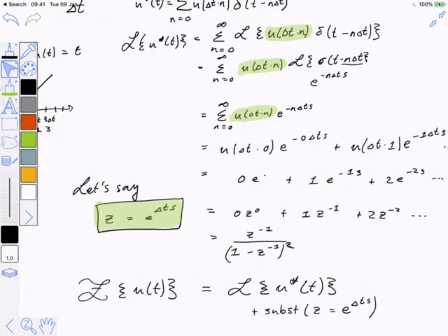Now, if you didn't go through this derivation, that wouldn't be 100% as clear, right? It all links back. So if you just remember how this derivation works, you know a whole lot about how the Z transform of a signal helps us to know the values at the points. I'm going to do the Z transform of systems tomorrow. But remember, we've done the first part now, right? We've been able to calculate the Z transform of a signal, and we know how to read the Z transform to get the values of the signal.